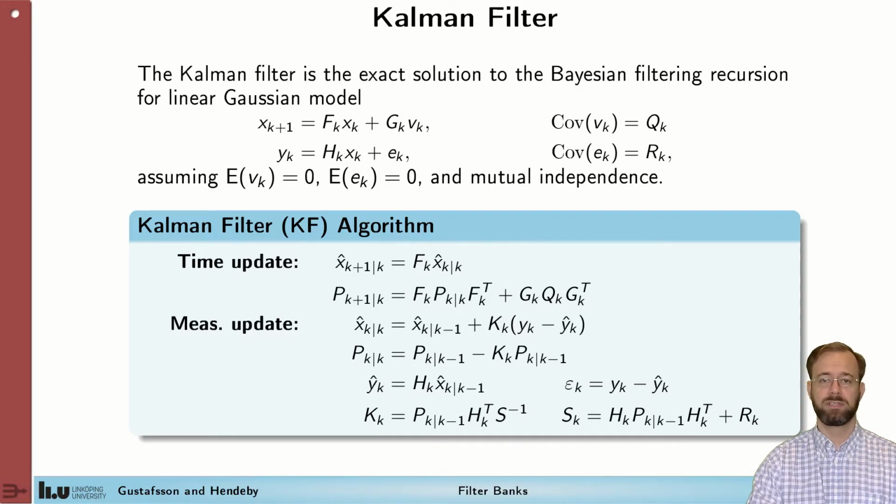The Kalman filter then becomes an algorithm in two steps, where we propagate the mean and the covariance of the estimate. The prediction step, or the time update step, simply predicts forward in time what happens to the state. In the process, we lose information as we don't know exactly what happens. It could be model errors or maneuvers, for example.